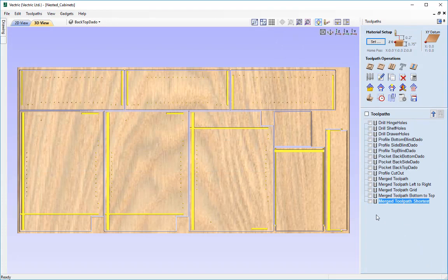Just to recap what we've demonstrated in this tutorial, we have learned if we have a single part which we would quickly and easily like to create multiple copies of, and having them set out in a grid fashion works with the shape of the part we are wanting to cut, and saving as much material as possible isn't really an issue, then the array copy toolpath would be the nicest solution.